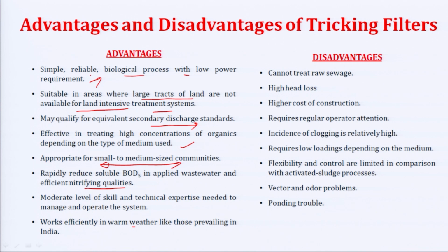You do not have to do anything more, right. But in cold places, imagine those filtering media left in the open, with the trickling filters there. It may get very cold, and those filtering media may get frozen, in the sense those bacteria will die. So, trickling filter is not going to work in those cases, right, or if you want it to work, you may have to heat up the whole environment, right.